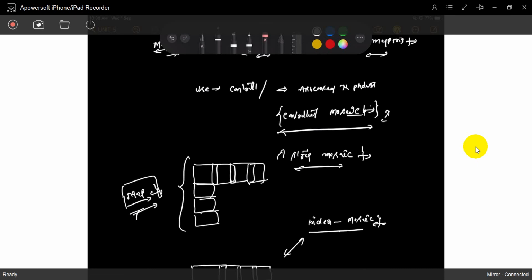Is that understood? So to get an idea about that location, you can use these mosaics. But to really maintain an exact three-dimensional view, we have to use software to convert into three dimensions. We have to take care of the parallax error and project it, and later we will get a three-dimensional view, with exact elevation and x, y, z coordinates. That is for the controlled mosaics. These are just a reference. Got the point?